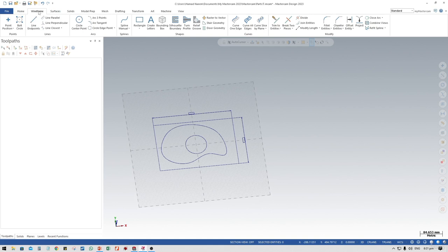So on the wireframe tab, you have 2D tools to make 2D sketches: line, circle, 3-point arcs, two arc tangents, circles, polar arcs, spline, blended spline from the curves, automatic, and convert to NURBS for surfacing purposes. And we have some rectangles here, polygons, ellipse, helix, and spiral also.